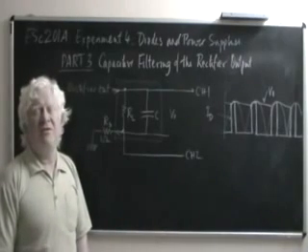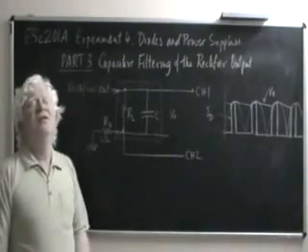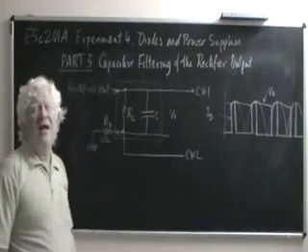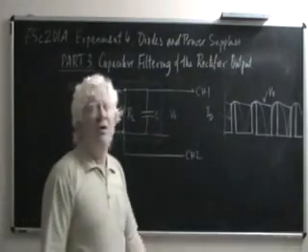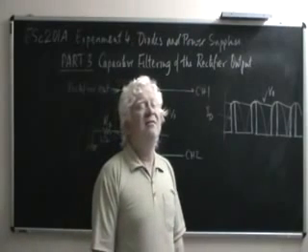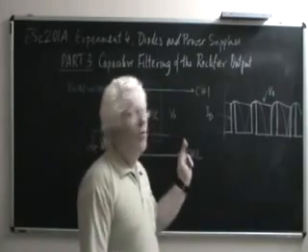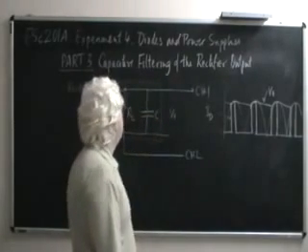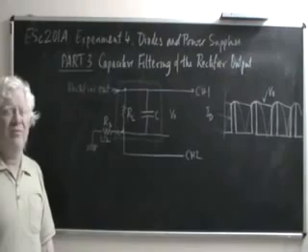So for a very large capacitance, when the diode gets forward biased, it is almost short circuited to the ground, except for RS and some internal resistances of the diode. So the larger the capacitor you put, the stronger is the current pulse, the higher is the amplitude of the current pulse. This is a caution to us that putting on a very large capacitor would give you a very level waveform, but it takes you to the risk of blowing up the diode by excessive forward current in the diode.